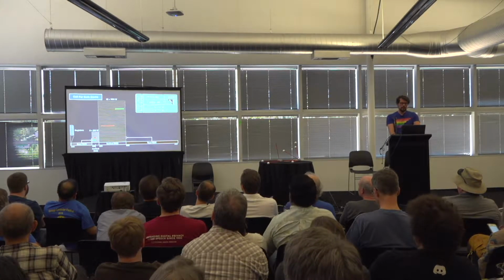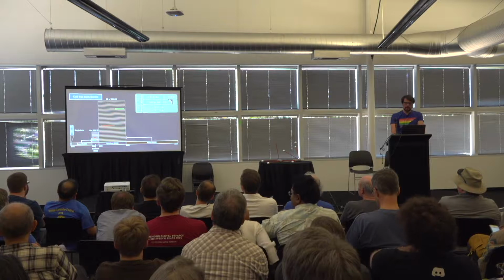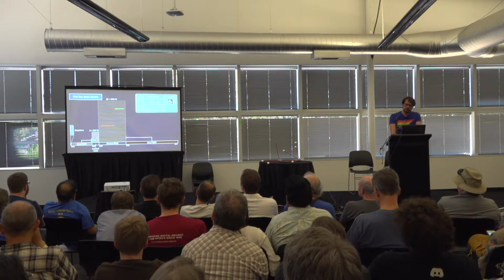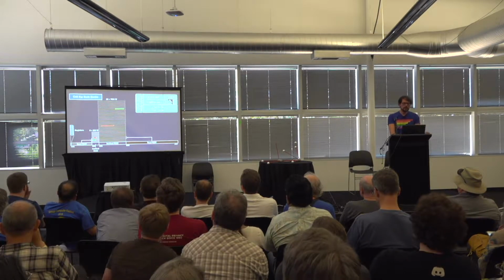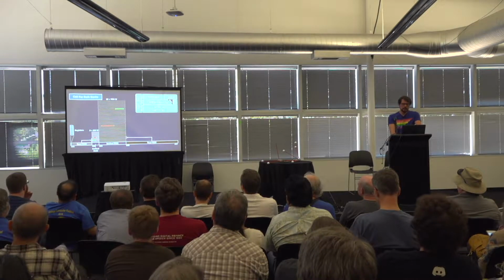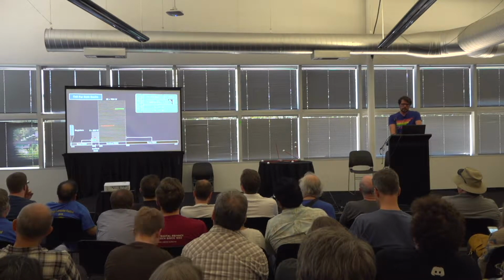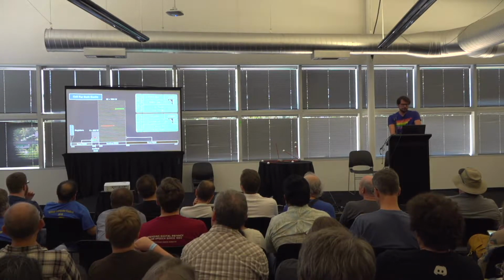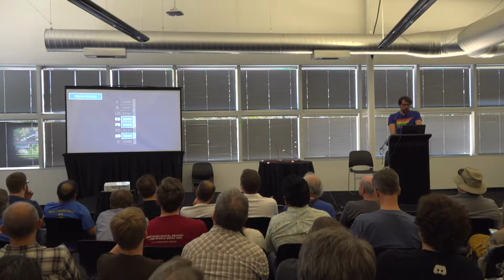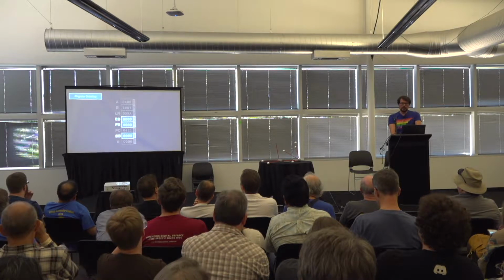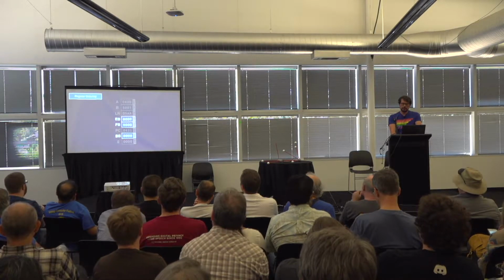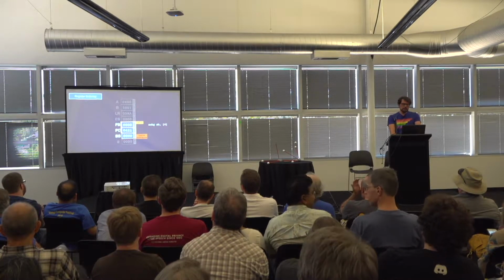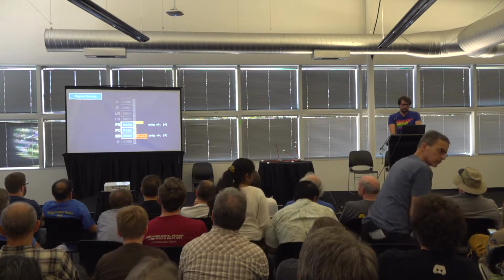Subroutines usually have their private variables on particular RAM banks. Call for both banks passes control to a function on a different ROM bank and also directly switches the RAM bank so that the callee can immediately access its variables. Return for both banks returns to the caller, restoring its RAM bank configuration. The unusual ordering of the bank registers was chosen to allow for a double word exchange of FB and PC, as well as for a double word exchange of PC and BB.